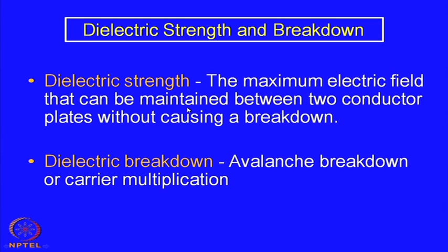But can we apply any voltage we like? The answer is no. We have a limit of electric field which we can apply for each material. So, the materials are also characterized by the maximum electric field that can be applied on these materials. Beyond that, what we call a breakdown takes place. So, there is a dielectric breakdown, okay.